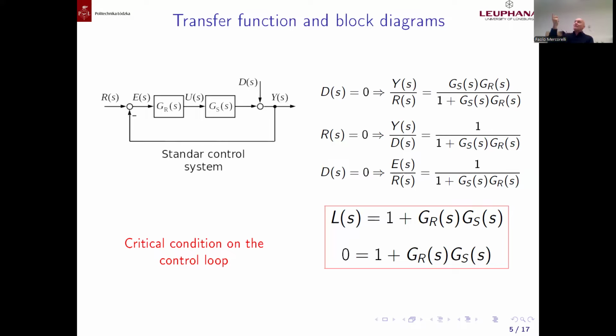Now, if alpha is positive, we have a function which goes to infinity. For a system, an answer which goes to infinity means that the system is unstable, if you consider the answer of the system as an exponential function with a positive exponent. This means the pole, s minus alpha, means s equals alpha, is positive, so the real part is positive.